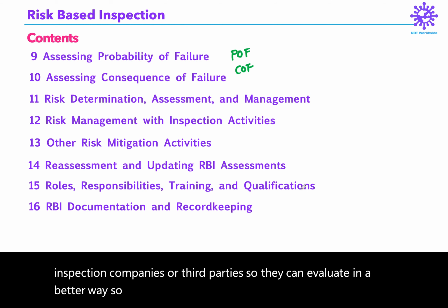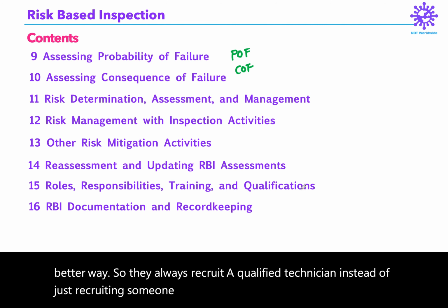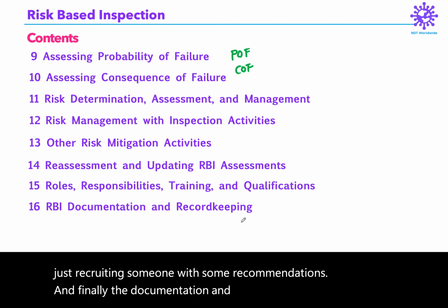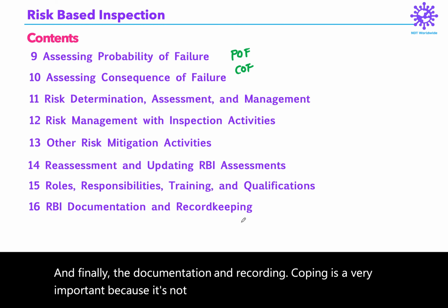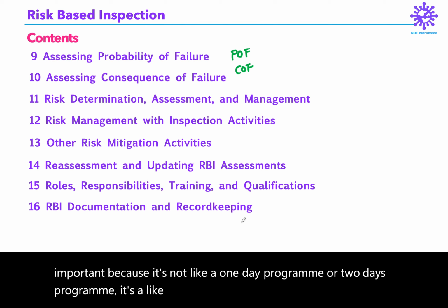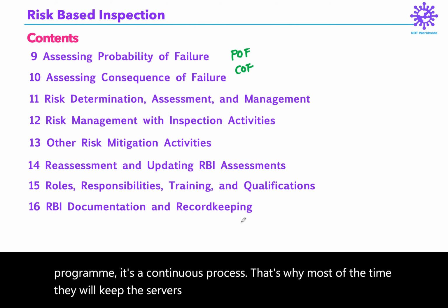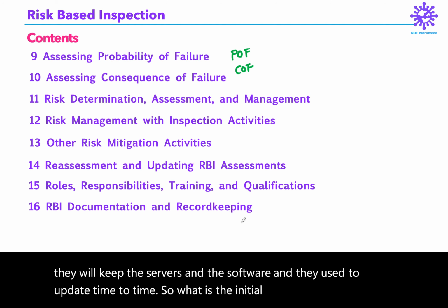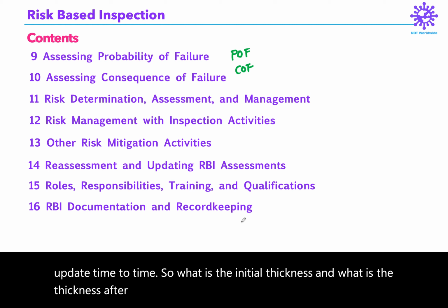So they always recruit a qualified technician instead of just recruiting someone on some recommendation. And finally, documentation and record keeping is very important, because it's not a 1 day or 2 days program. It's a continuous process. That's why most of the time they keep servers and software, and they update from time to time. What was the initial thickness, what is the thickness after 5 years, and what inspections they did. Same as a hospital medical history.